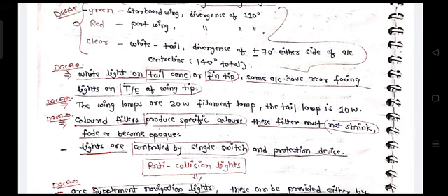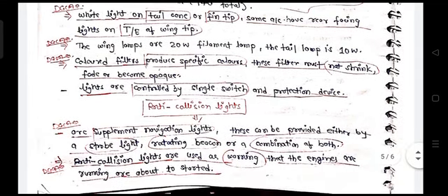That means an aircraft can be located from all 360 degree angles. That's how the lights are designed and radiated from an aircraft. From the left 110, from the right 110, and from the back 140. So 110 plus 110 is 220, plus 140 means 360 degree. All 360 degree of coverage will be given by these three lights. The white light is usually at the tail cone or fin tip. The trailing edge of the wing tip can also be used. Usually the wing lamps are 20 watt only, and the tail lamp is 10 watt. So the wing tip lamps are a bit more powerful.